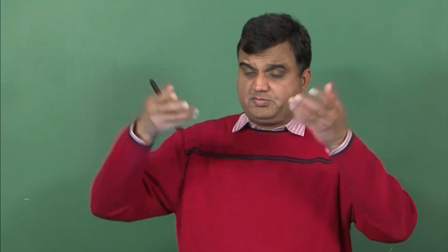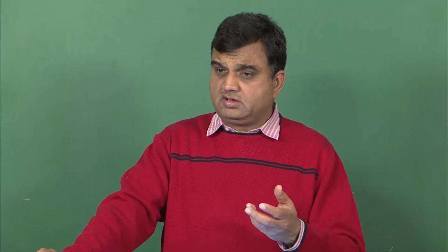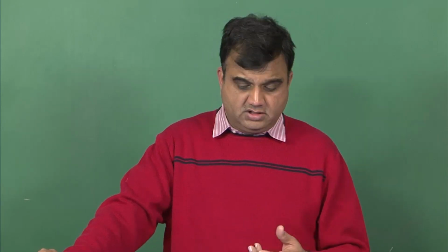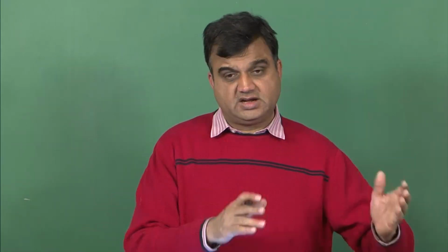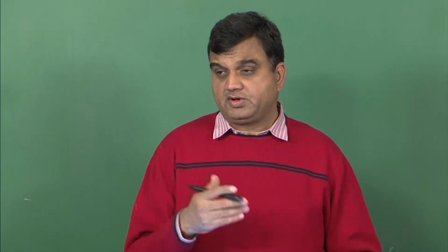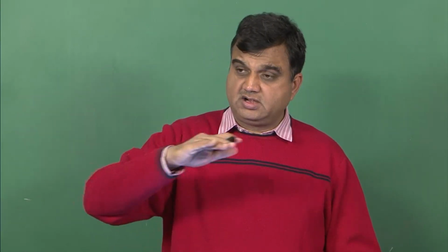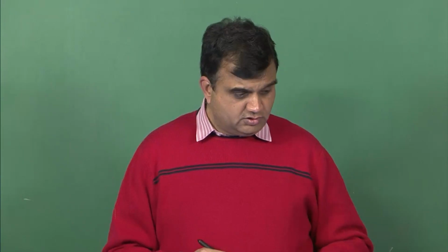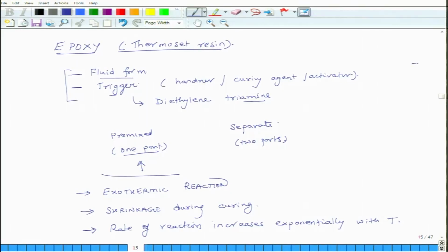But if you raise the temperature very high, then the curing will be fast, but the quality of the curing may not be great. Okay. So, there are some standard guides as to what kind of temperatures should be maintained to make sure that curing is of a good quality. So, this is about epoxies.